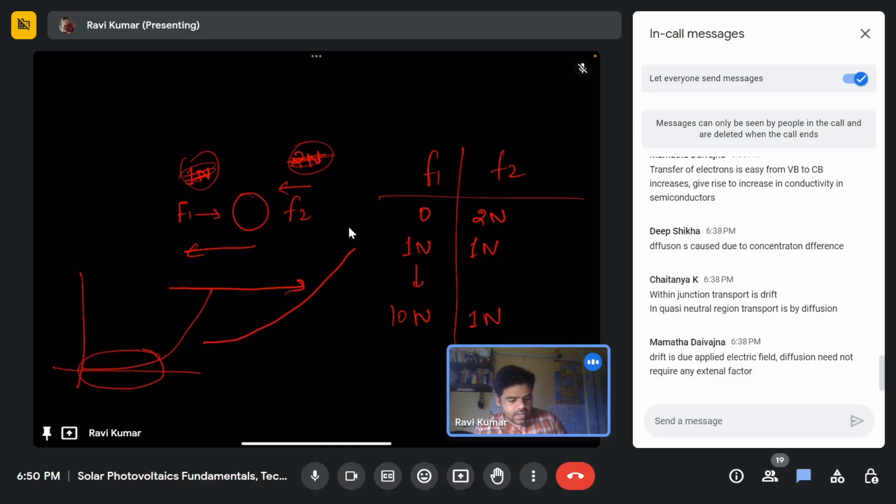If our external applied voltage is comparable with the knee voltage or PN junction potential, then the current flow will be very low. But if the external potential is much more than the knee voltage or PN junction potential, then the change in current will be more, or an abrupt change will take place.